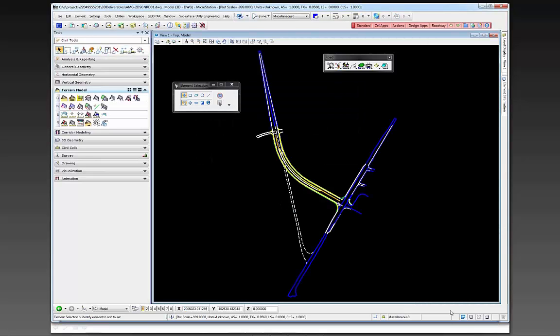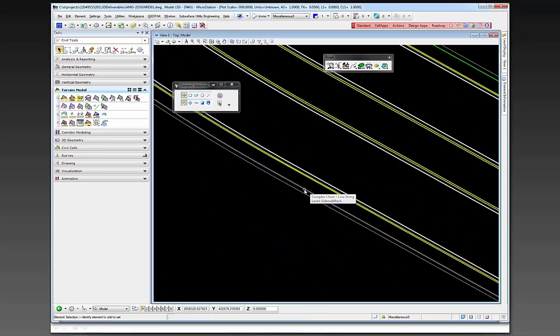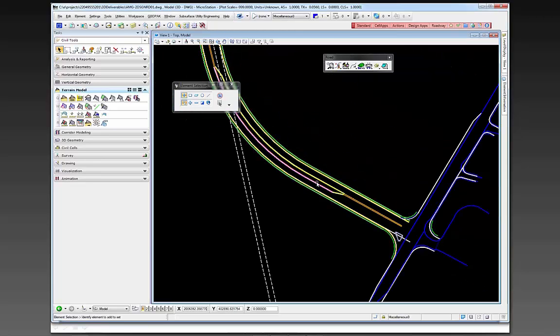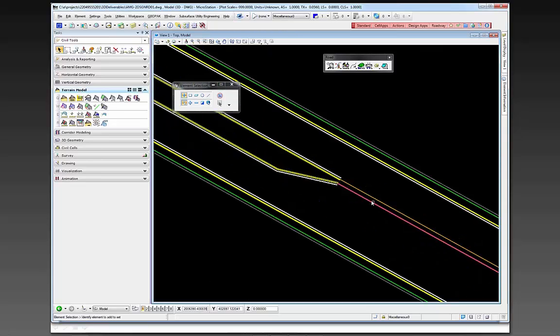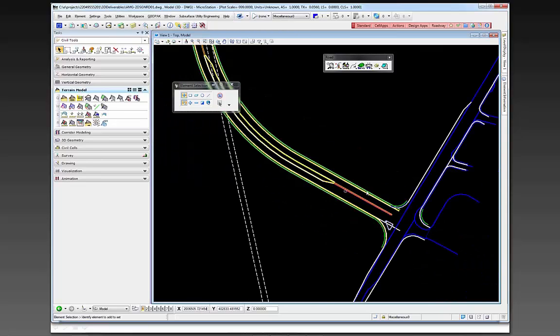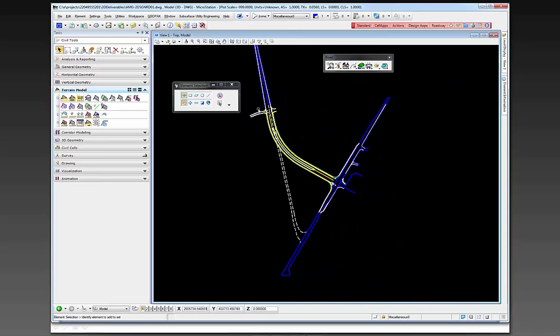And then you'll see that now I'm in this DWG work mode. So I have a DWG file open, which I like to see because then I can go in here and verify that the level names are basically accurate and they look correct, so that if I had to give a DWG file just to a contractor, I would know that it looked like my proposed planimetrics, and it gives me a way to kind of do a QC on it. That is the 2D planimetrics.